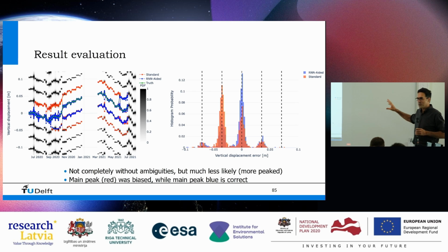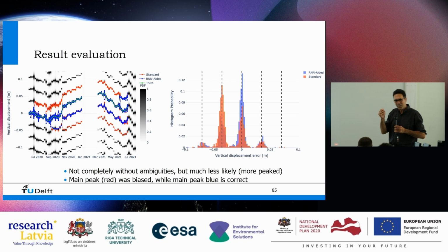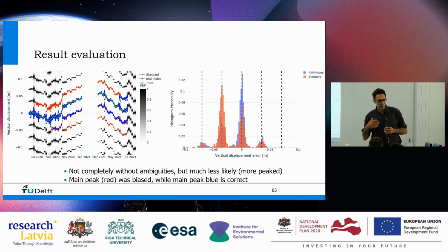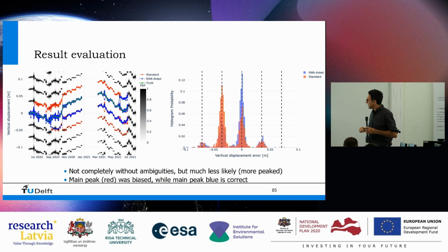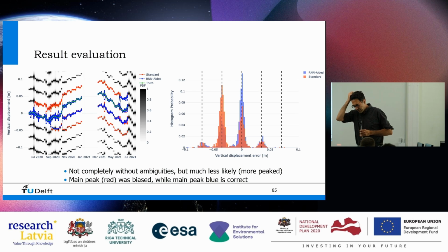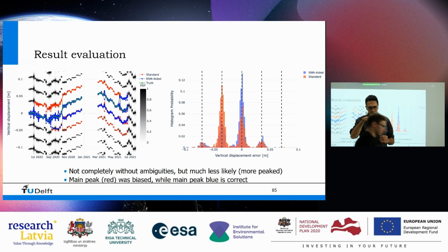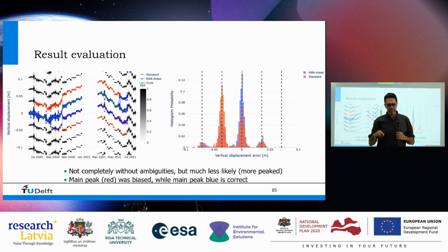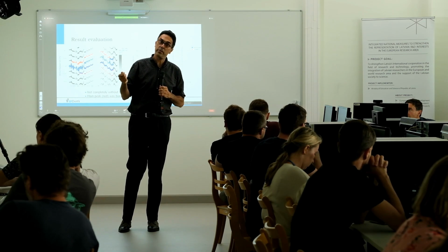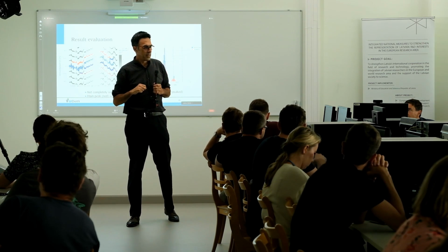Okay, so this last part was basically into our research, just to tell you what we're working on at the moment. I think that's a good point to wrap it up. So what I tried to do today was to give you an overview of InSAR, how it works. We start all the way in the beginning with this intuitive feel of the sensitivity to topography on the interferograms, why it is that we can measure deformation 1,000 times better than topography or elevation.